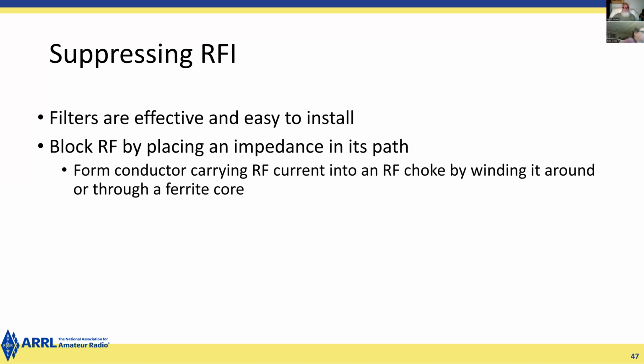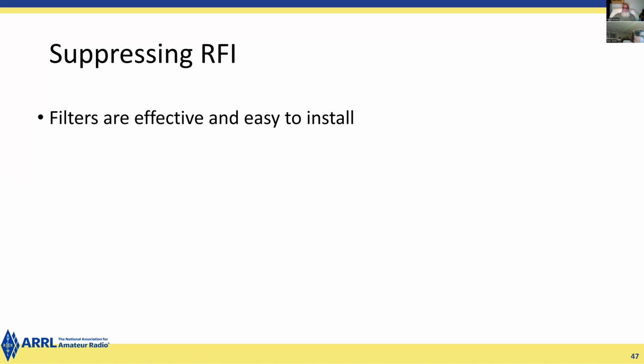So if your computer is controlling your radio, for instance, by USB, the USB connection can be broken. That's very common, especially on the newest transceivers, which have a direct USB connection between the radio and the computer. The solution I've found that a lot of people use is a printer cable that has ferrite beads on both ends of the cable. And that's very effective in stopping any problems with computer control.